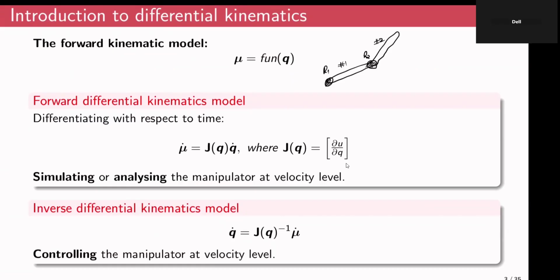you basically define the configuration of a robot using two joint variables. I can denote it using two angular coordinates, maybe this being theta1 and this being theta2. And maybe at the end of the robot's arm, you have the end effector, could be a gripper or a welding gun, any sort of end effector.